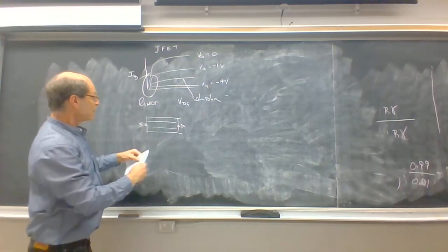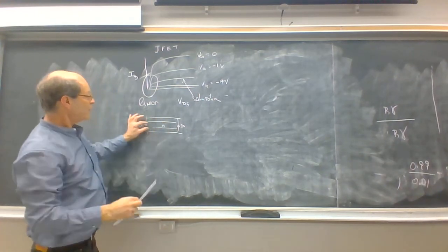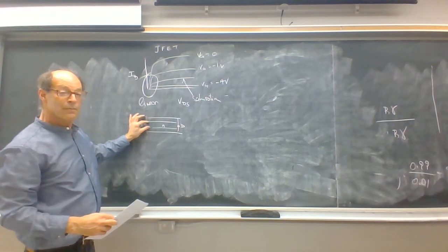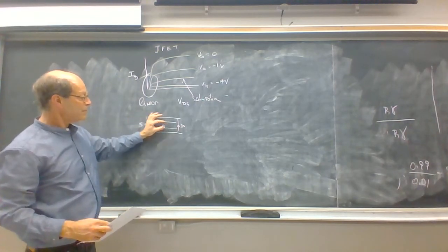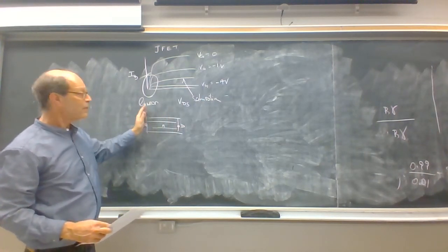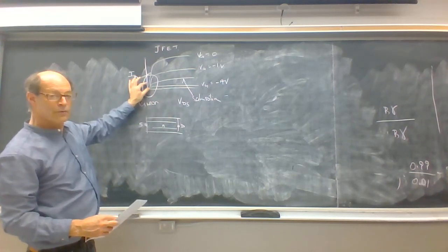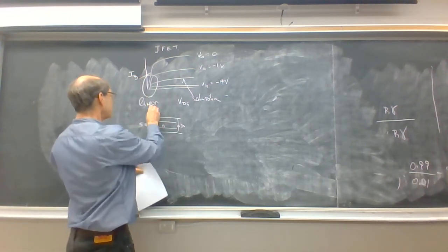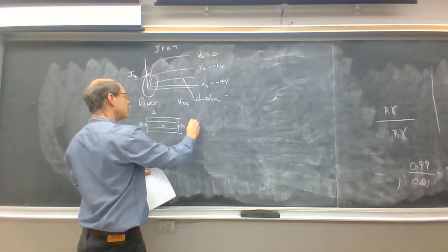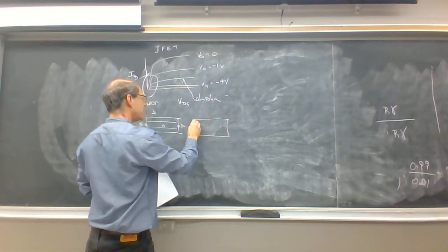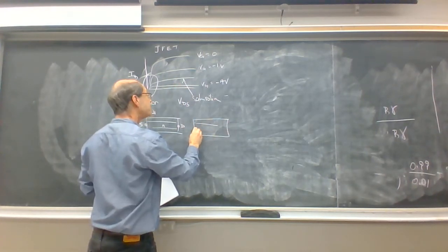So we can consider the channel to be virtually parallel with not much change in width from one side to the other at these very low voltages. So that's a linear regime. As you get to the pinch-off regime, the channel width starts to pinch off.